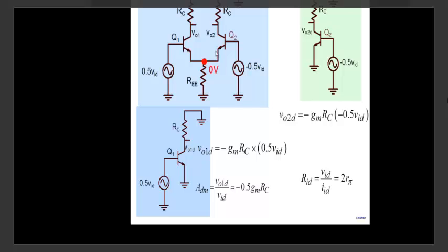Through the early voltage. And if the early voltage is large, and these voltages are not so large here, then even though the voltages here and the voltages here are different, it doesn't have too much of an impact, because the collector voltage does not have a significant impact on the current flowing through the transistor once the transistor is in forward active mode.